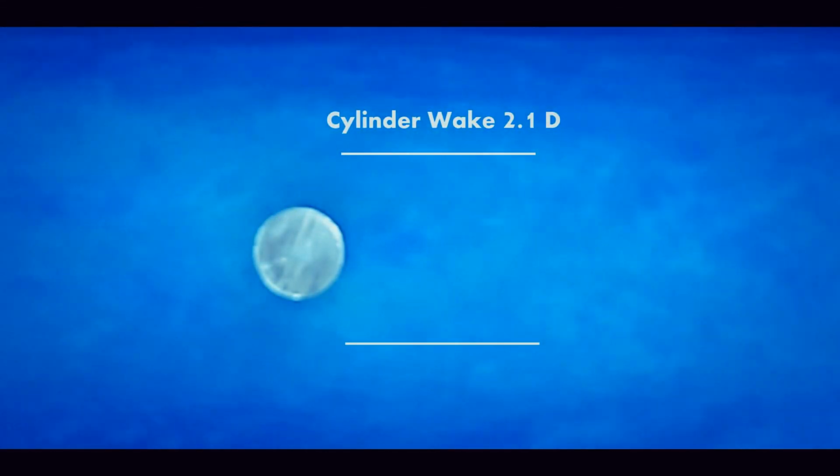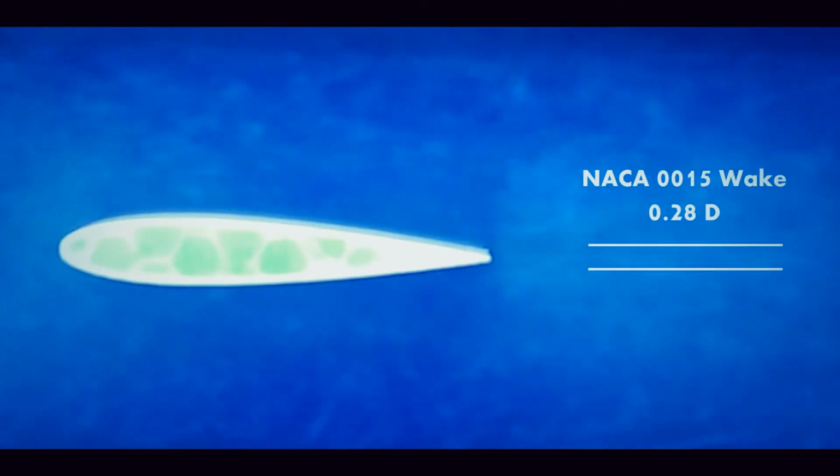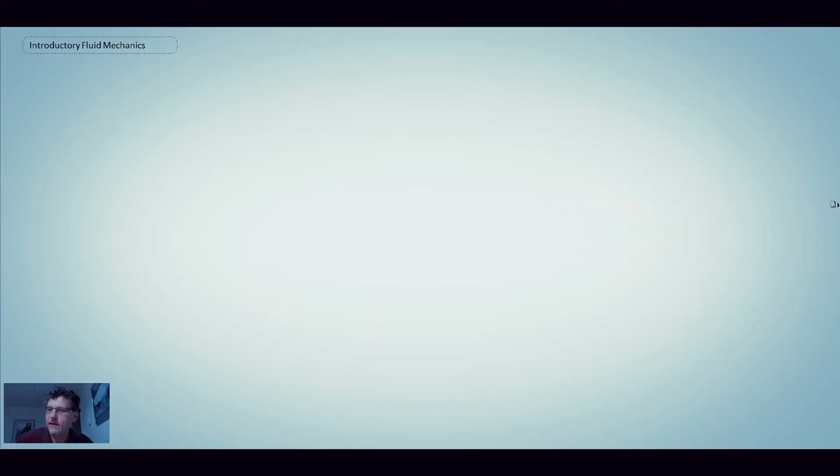I crudely measured it, 2.1D. Here is the ellipse, wake width about 0.77D, thinner than its thickness. And then finally the NACA 0015 wake width about 0.28D. That's a fairly crude estimate with just me looking at the video and trying to estimate what those values would be. Let's write those down and compare them to the drag coefficients for these objects.